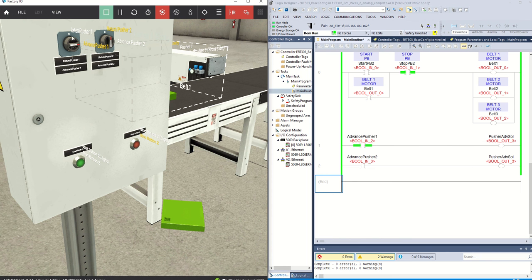So if I switch these switches the other way and turn this output on, you'll see in this case now, this one actually turns it on because this one happens last. This is the one that actually controls it, and now we have the output on even though the logic to the left of it is false.